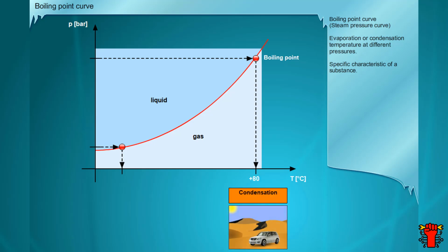Even in a 50 degrees Celsius desert, the condenser should still give off heat to the surrounding air in order to liquefy the refrigerant. The boiling temperature must therefore be much higher. On the other hand, the evaporator must also operate at low outside temperatures, such as for the reheat function, in order to make the refrigerant evaporate. The boiling point must therefore be quite low.